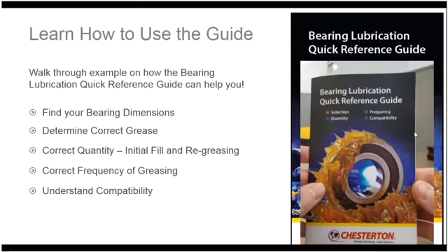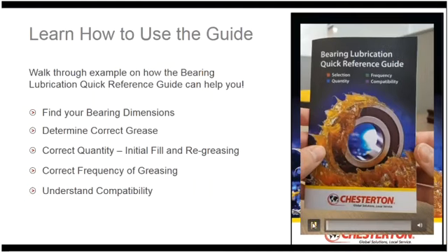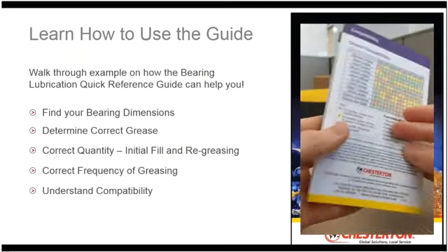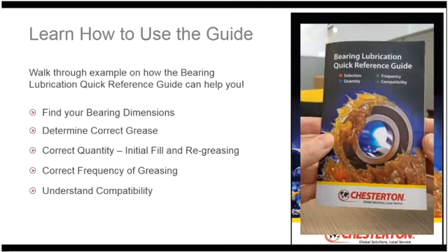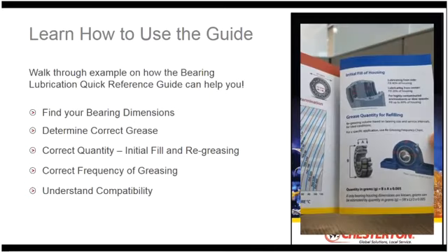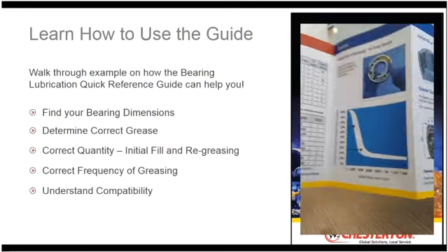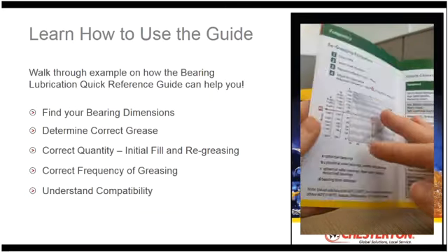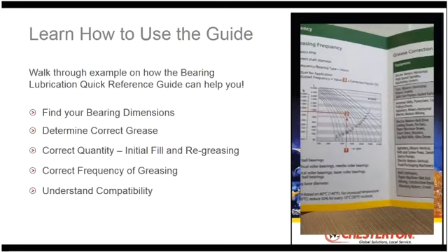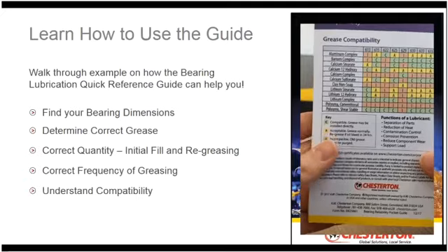We are going to learn how to walk through the latest Quick Reference Guide, which will show us how to select the correct grease, select the correct quantity for initial fill and regreasing, select the correct frequency of greasing, as well as understand the compatibility of different grease types.